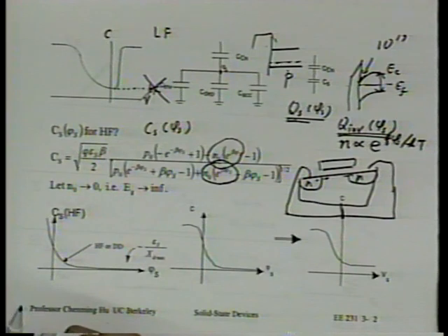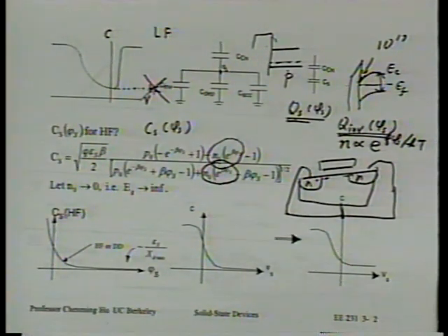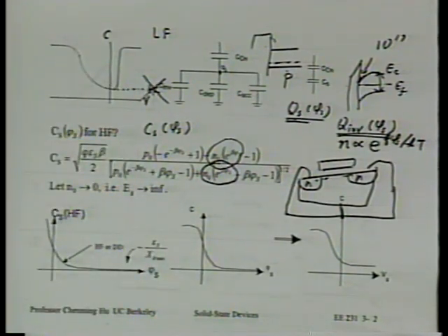When the AC current is so small, you're going to have a hard time measuring that with the capacitance meter, because a capacitance meter is based on measuring the AC current inside of this meter and dividing that by the AC voltage, and it also looks at the phase. It's a vector ammeter, and that's how you get a capacitance reading from the capacitance meter. So when the frequency is low, the capacitance current is very small. You won't get a very accurate reading, right? So it's actually never practical to try to get a CV at low frequency.